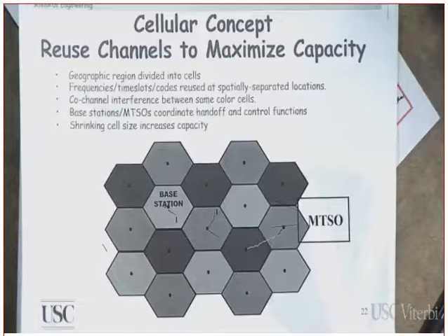And the receiver. Even that inversely proportional to the square of the distance, this is assuming we are operating in an open environment, like in a rural environment. Rural means what? There are no tall buildings, not too many obstacles and stuff like that. But if you are working in a dense environment like, for example, in downtown LA, the signal power will degrade inversely proportional to probably the distance to the power what? 4. Or even more than 4 in a dense environment or even in a suburban environment. Did you get this or not?